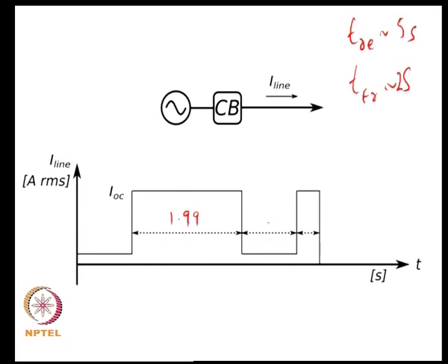And suppose this duration is 1 second, then during this particular 1 second the circuit breaker was going through a reset action. So, to fully reset it would have required 5 seconds. So, in 1 second it would have reset by 1/5 of the reset value. So, it would be at this particular point, at 4/5 of the value to actually trip the tripping device.